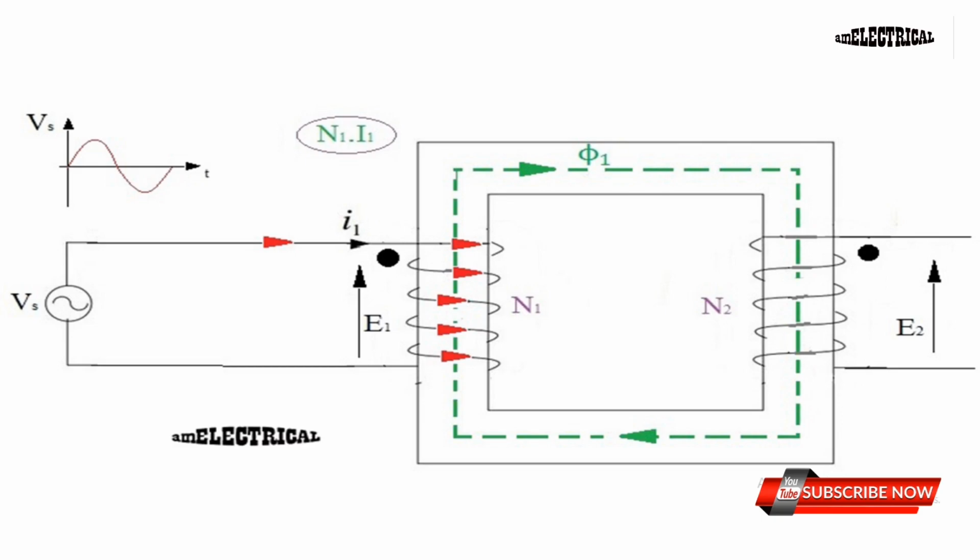Initially, the load is not connected. First, we are connecting the primary winding, whose number of turns is N1, with the supply voltage Vs, and I1 current starts flowing. According to Ampere's law, the flux phi1 is generated by the influence of MMF N1 I1, that is ampere-turn, and its direction is upward, which is decided by the right hand rule.